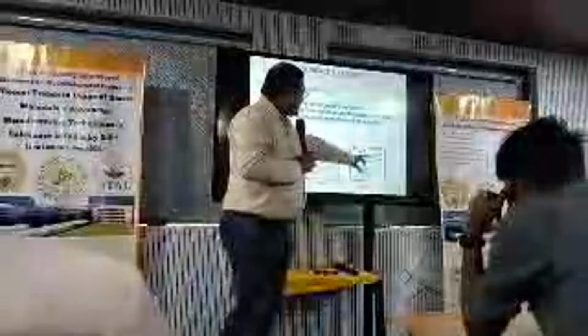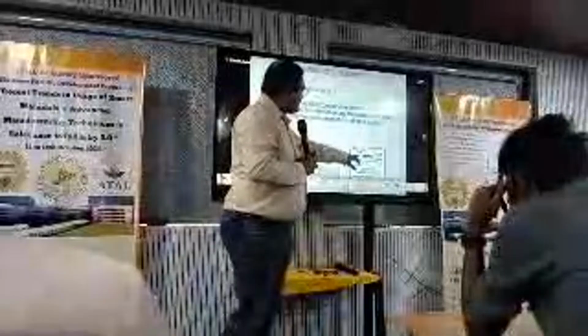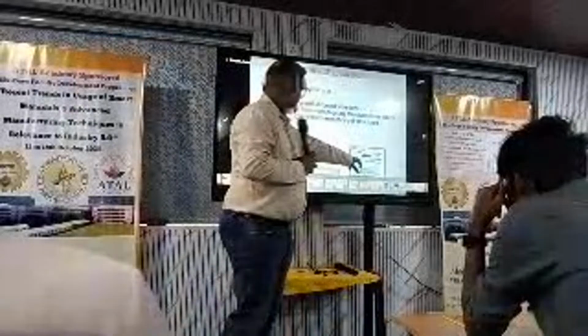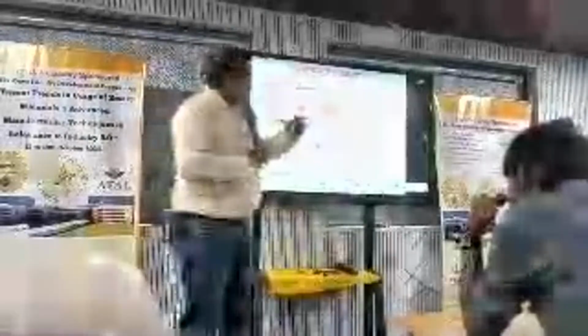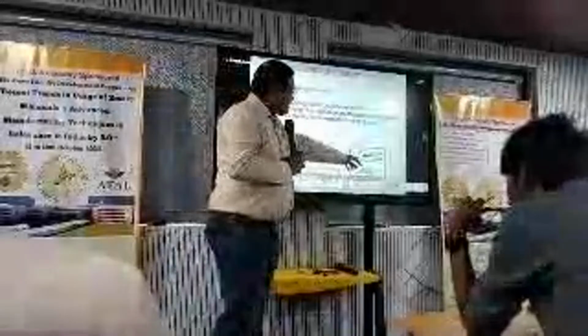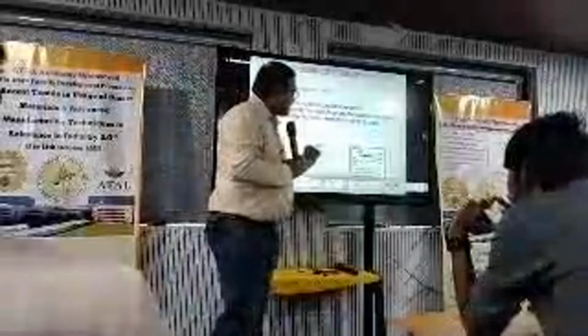This is the viscoelastic layer. Above that, one more layer is there, a constraining layer having 1/10 of the thickness. Let us assume this is 10 mm and that is 1 mm thickness is required. That will reduce the energy by using the bending of the waves. These are the two types of structures.